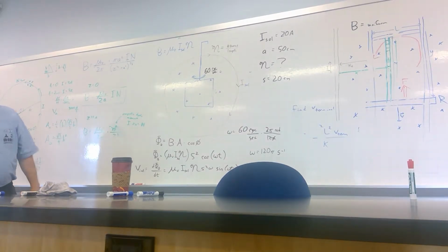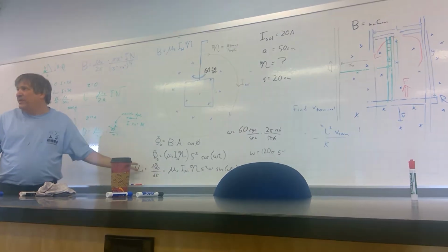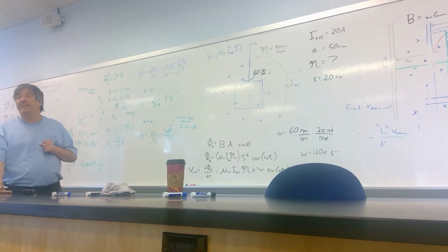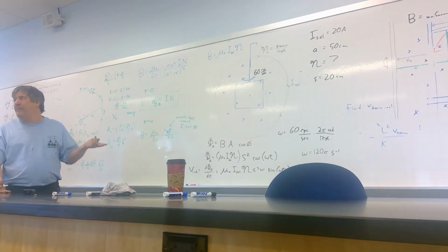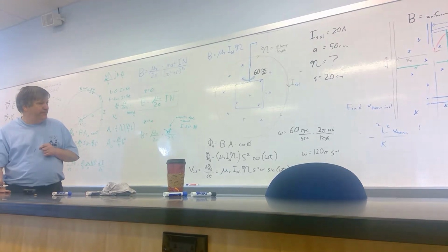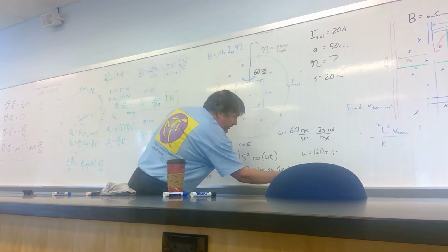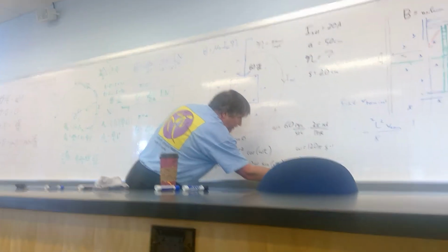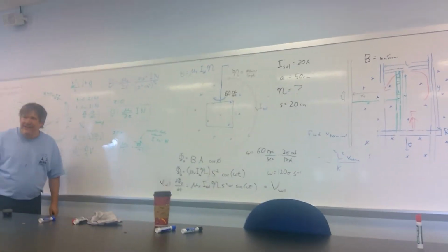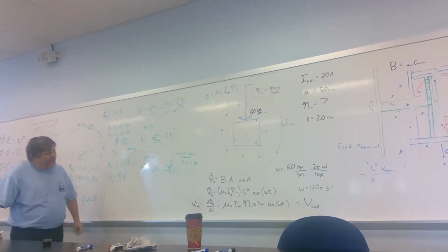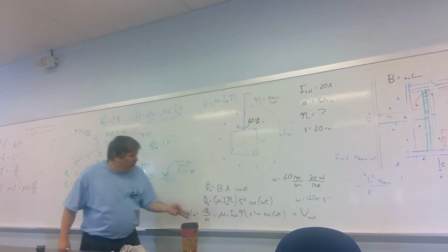What is the amplitude of that voltage? There's my expression for the induced voltage at any particular moment. But if I said I wanted the amplitude of this thing to be 110 volts, would I need I max? I could just set this whole thing equal to the voltage of the wall outlets, set it equal to 110 volts. But I kind of feel like I'm trying to solve for N. Do I know all the rest of this stuff?